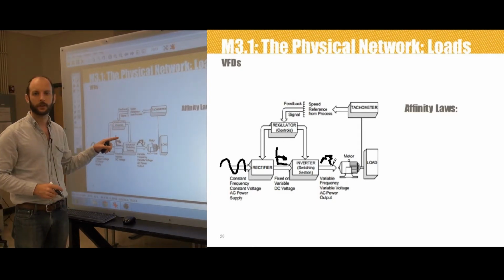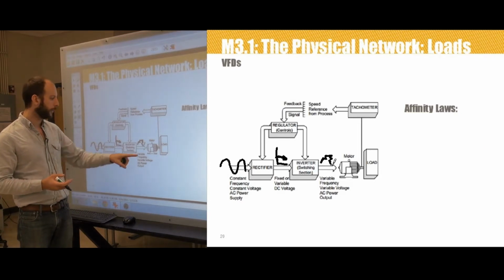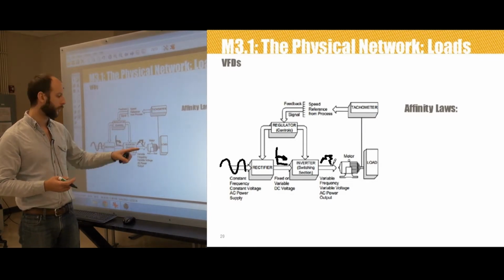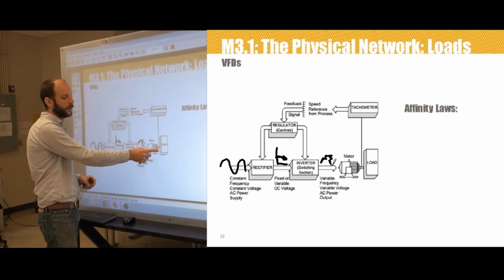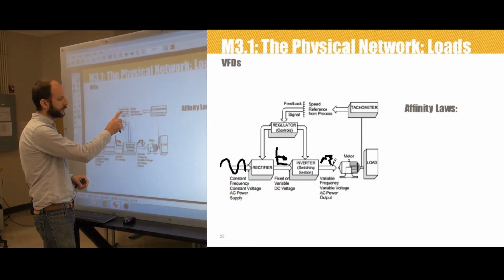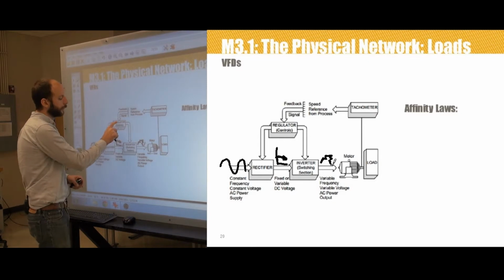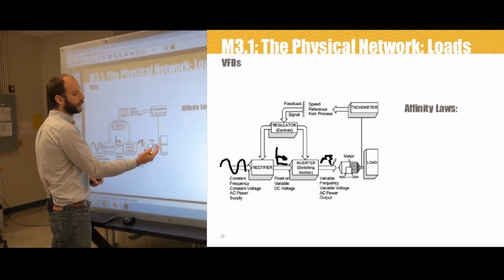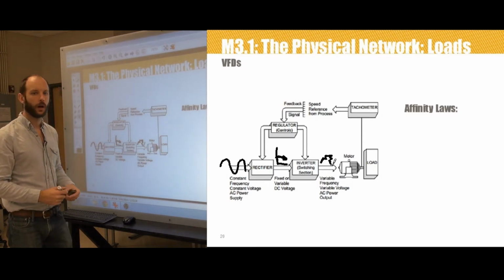Here we show that on most VFDs, there's a regulator, and what it does is it modifies the inverter switching characteristics so that the output frequency can be controlled. A lot of times it uses sensors, in this case a tachometer, to measure the controlled variable, which in this case is motor speed. So as I adjust the load on the output device, the tachometer is going to see how that change in load affects the RPMs of the motor. It will then send the speed signal through a controller. The regulator acts as the controller. In this we're showing it acts on the rectifier and the inverter, but typically it influences the switching algorithm in the inverter, which will then change the output waveform to bring that speed back up to what it was, or reduce that speed back down to what it was before the load change, right?